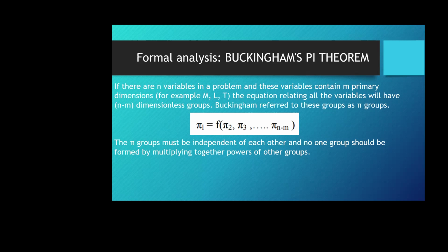And then, of course, you have the equations, and you start to play with them, and this is the Rayleigh method. This is what helps you to evaluate consistency of the units, or helps you to guess more or less what the power is, how the two variables are correlated. Because if you have one variable inversely proportional to another variable, but you don't know which power that inverse proportionality has, it could be to the square, cubic, quartic, 1/2, anything.